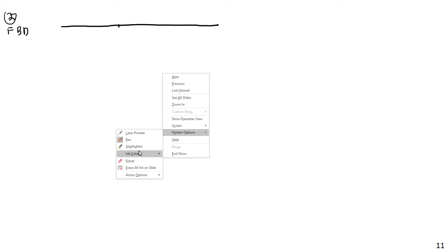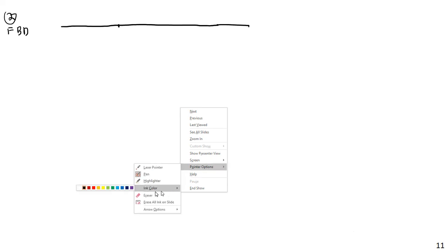So I'm going to put all the forces that I have. Maybe I'll draw it like this. I'm going to have all sorts of trace lines on this one. So here, I have my 19.5 kip force here. And notice in my large free body diagram, my final free body diagram, I lose any distinction between reactions and loads. They're just loads. They're just forces at that point. It doesn't matter whether they're restraining reactions or original applied loads. They're all the same thing as far as the beam is concerned. And then I have 92 kip feet here.